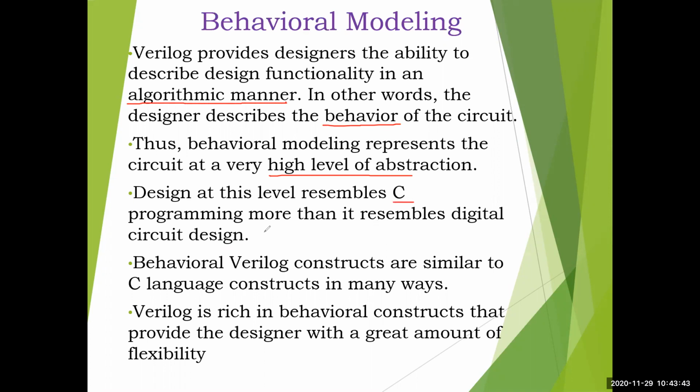So at this level, the program looks like C programming more than a digital circuit program. Verilog constructs are similar to C language constructs in many ways, like case statement, loop statement, if else, all this. Only the writing may have little changes. Verilog is rich in behavioral constructs that provide the designer with a great amount of flexibility. So these are some of the advantages of Verilog with respect to algorithmic decisions or the behavioral modeling aspect.